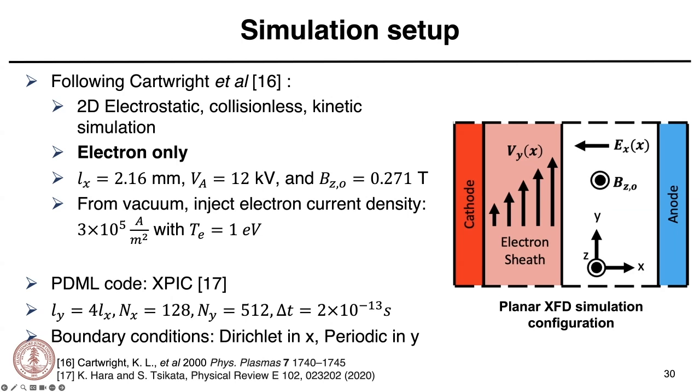I've been working with a fixed cell size, but something more variable could let us confirm that things are well resolved. I did a convergence study to land upon these cell discretizations, but it's still a question mark whether I'm resolving the Debye length well right at the cathode surface.